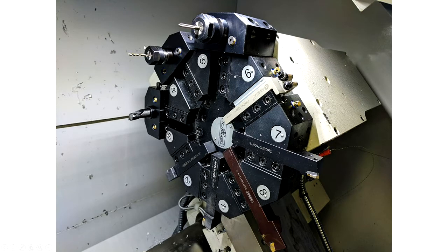And then we have these drills and taps and mills that point in the same axis as the spindle, and those are called axial tools. So the turret will position so that this tool is on center line of the z-axis, and it can only do operations on the center line.